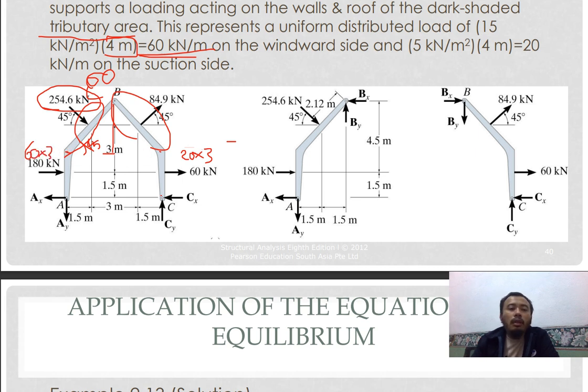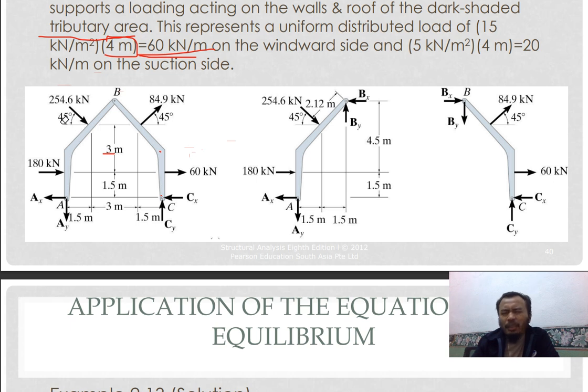So next, you now know the value of the peak load, the peak force. You can see the cumulative force acting on the beam, acting on the member due to that distributed load. Next, you want to know where that force is acting.